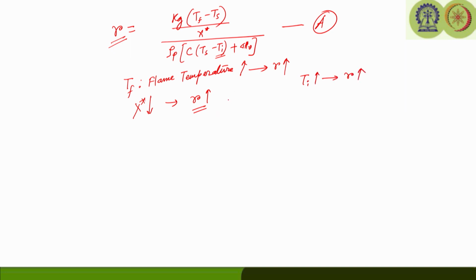So, there are various influencing factors which are going to influence the burn rate, but the reaction rate is going to be very much dependent on the pressure, as we have seen in case of the double base propellant. If we relate the standoff distance with the reaction rate of the propellants, we may find out that the pressure has a major effect on the reaction rate, and that will reduce the flame standoff distance. So, as we have higher reaction rate, the flame standoff distance is going to decrease as we increase the pressure, because the pressure has an influencing role on the reaction rate, and that will decrease the standoff distance.